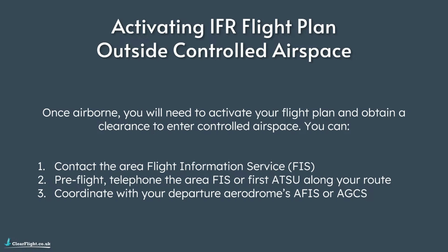One last thing that's worth mentioning before we move on to the rules and regulations is that if your flight is wholly outside controlled airspace, if you're flying from one uncontrolled airport to another and you're not going to enter controlled airspace at any point along the route, then ultimately there is no need for you to obtain a clearance to enter controlled airspace.